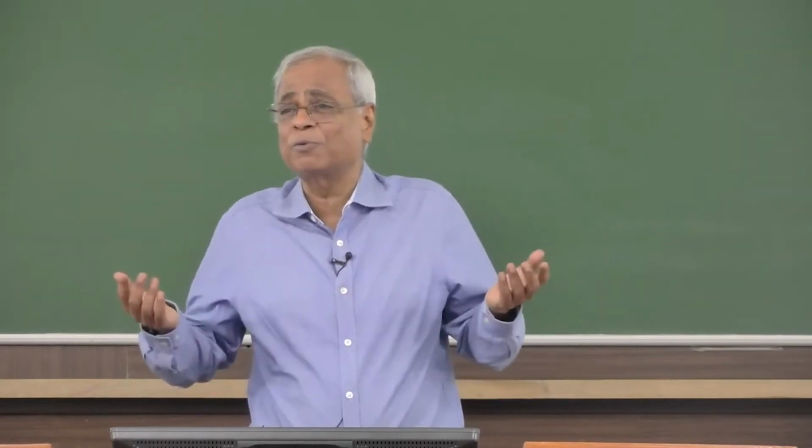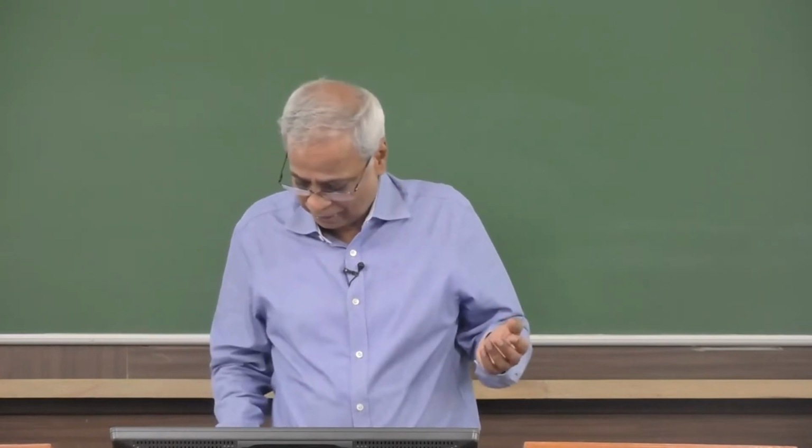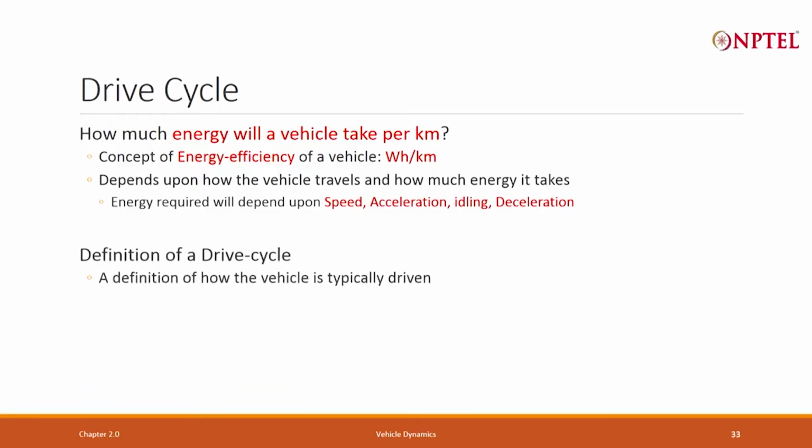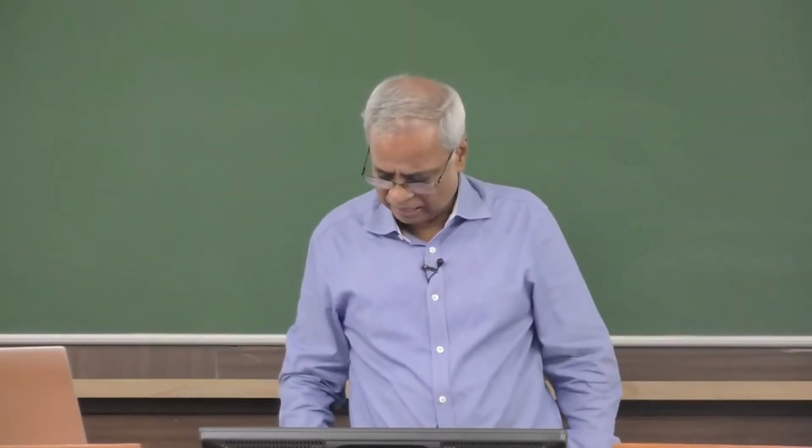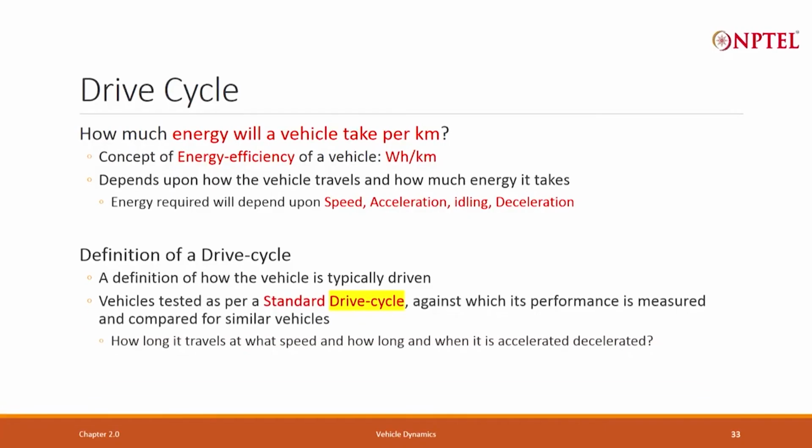Therefore, how do you now talk about watt hour per kilometer? You can talk about watt hour per kilometer by defining what is called a drive cycle. This, by the way, is done for a petrol engine, and is also going to be done for electric vehicles. It is a standard, a standard drive cycle. A drive cycle is a definition of how the vehicle is driven. It tries to standardize the driving pattern. Vehicles are tested as per standard drive cycle.